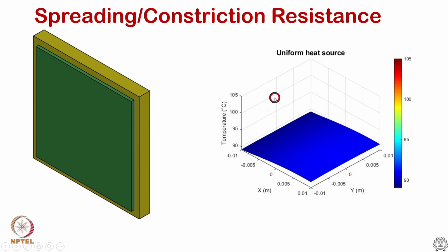We observe the temperature rise, and you can see that roughly 92 degrees Celsius is seen as the air contacts. It is much cooler at the entrance, where the air is cooler. But as air flows across it, the air temperature also rises, so the device temperature also rises owing to the boundary layer that grows on it. So, this, as you can see, is the situation.